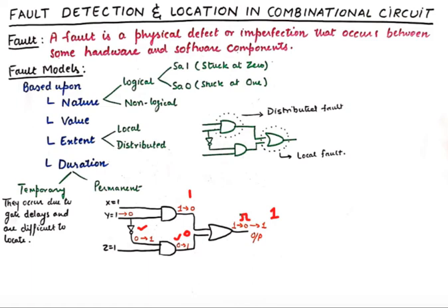and this is explained very well in my other video, which is on static hazards. If you want to see the condition where you get this kind of a scenario when one input is going directly into one gate and its inverse is going into another, that causes a static error, stuck at 0 and stuck at 1. So you could look at that, but you can understand while transitioning, this 1 will temporarily go to 0 and then will become 1 again. So this kind of an error is temporary in duration, but nevertheless it's a fault.